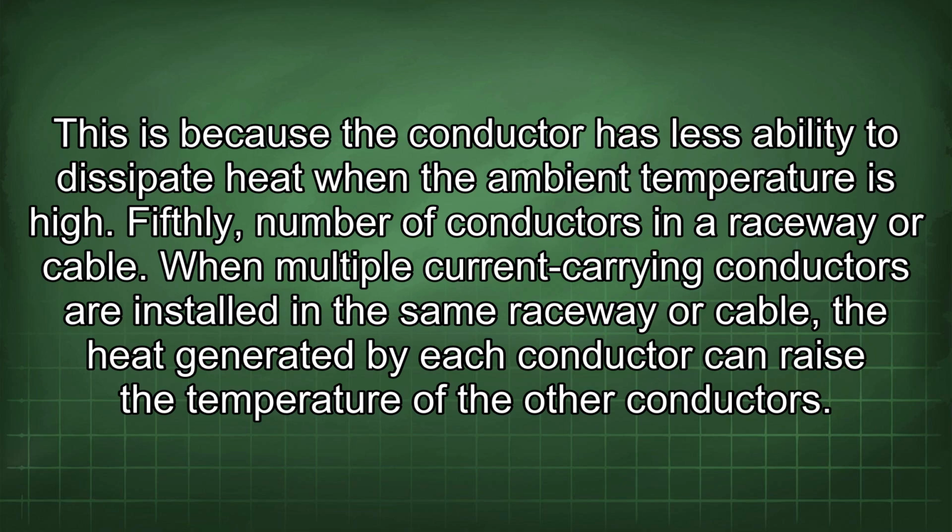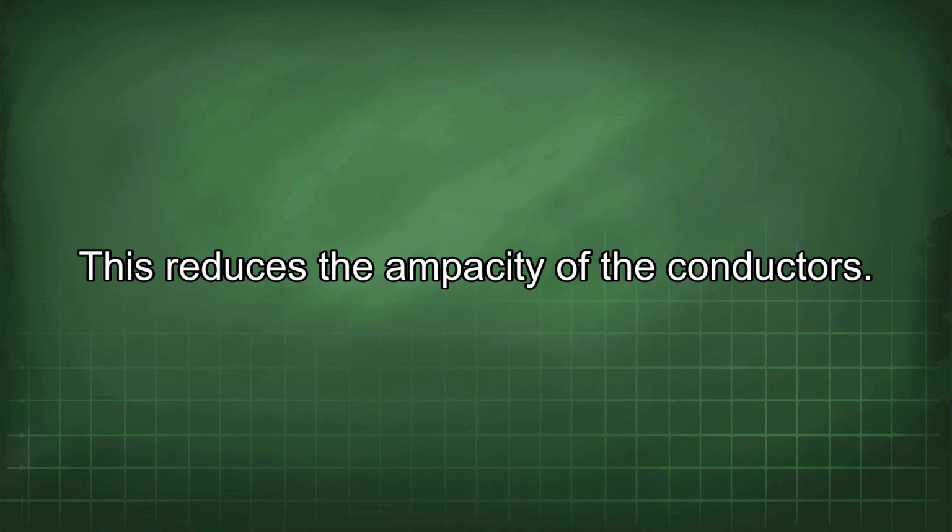Fifthly, number of conductors in a raceway or cable. When multiple current-carrying conductors are installed in the same raceway or cable, the heat generated by each conductor can raise the temperature of the other conductors. This reduces the ampacity of the conductors.